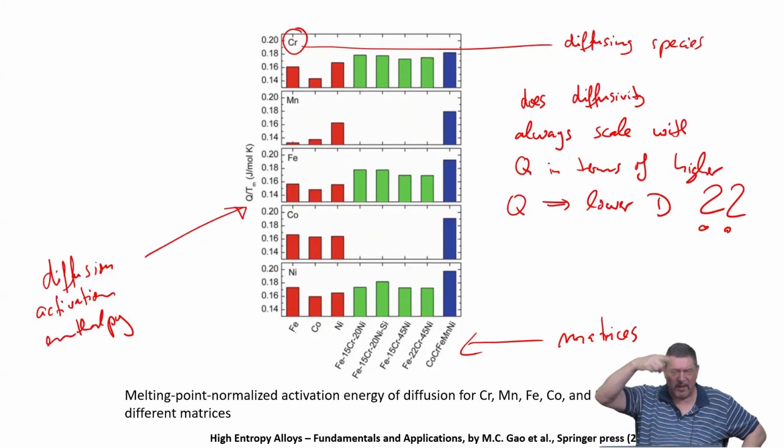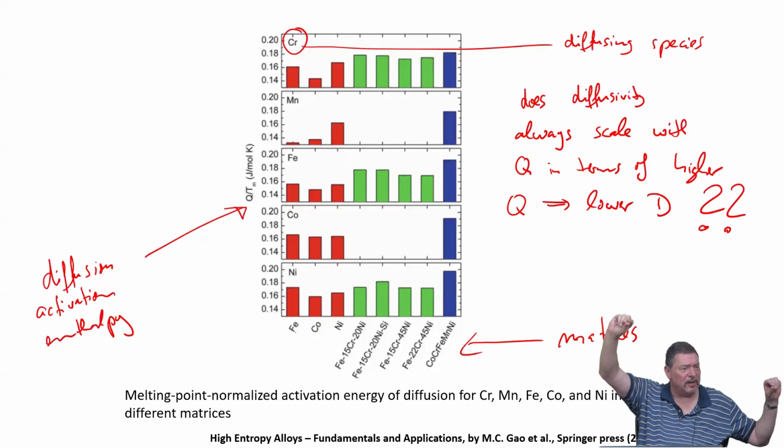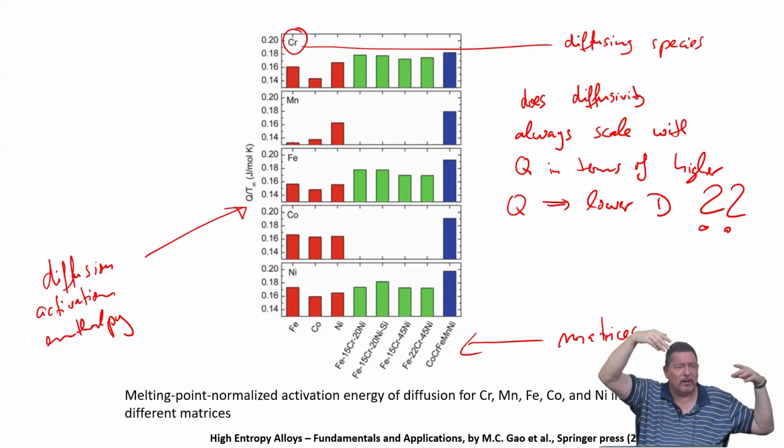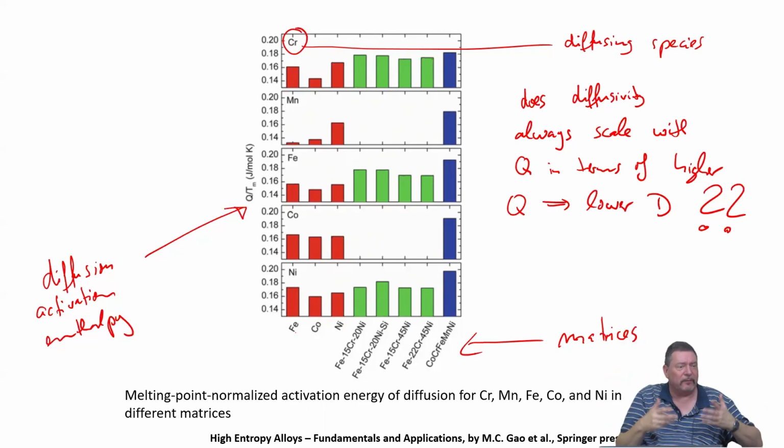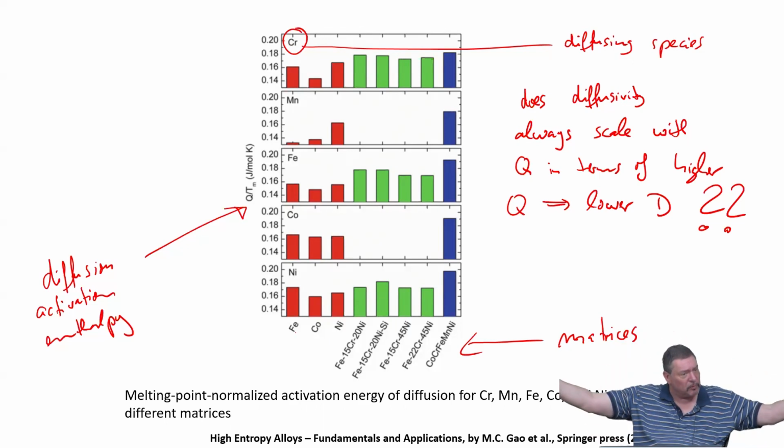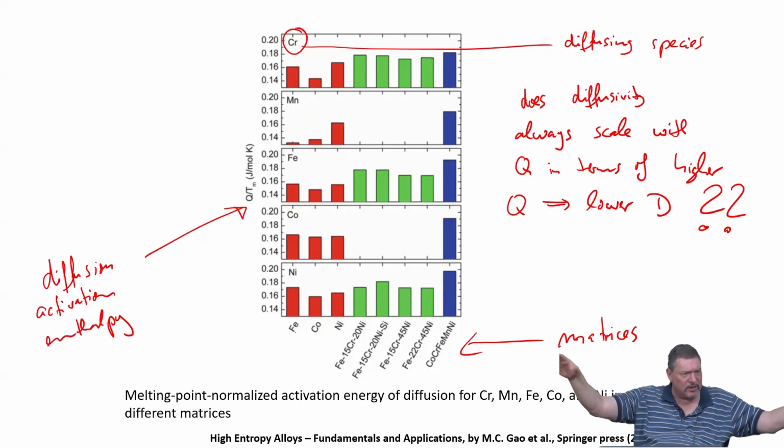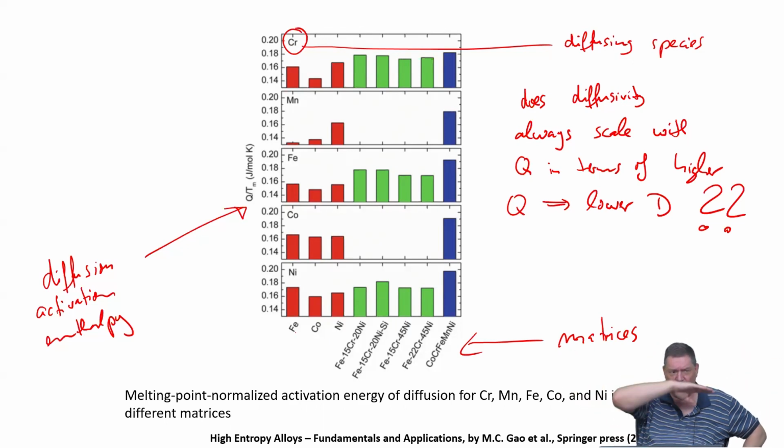Well, diffusion is many jumps, right? At what temperature? Yes, but you would say it's an Arrhenius representation, and the activation enthalpy is taken from the slope. So as long as the temperature dependence is the same Arrhenius dependence, then Q is a given value for a certain range of temperatures. It could not be too high a range because then the mechanisms change, but within the given range, you would say there is one Q, one activation enthalpy for this type of diffusion process which is dominant in the material.